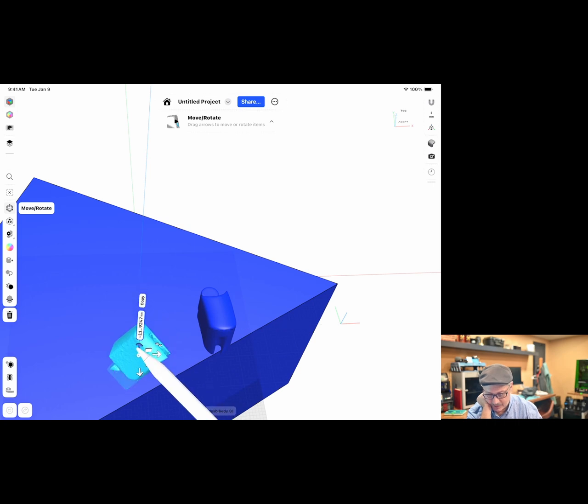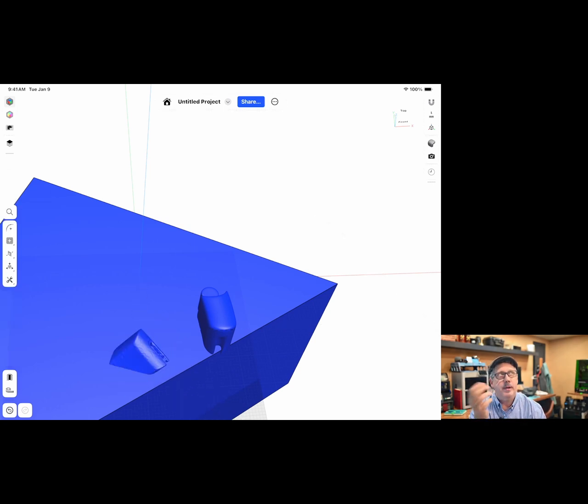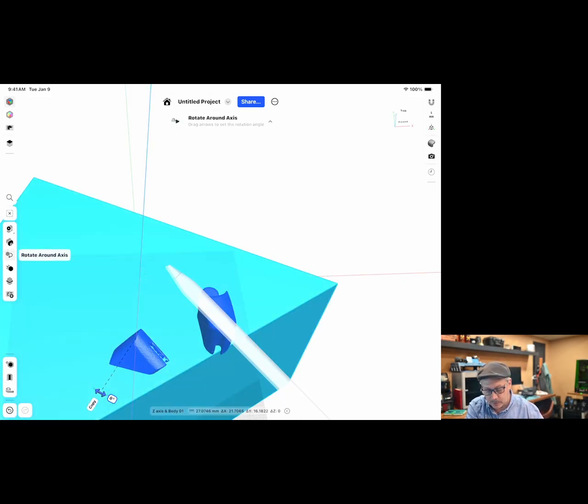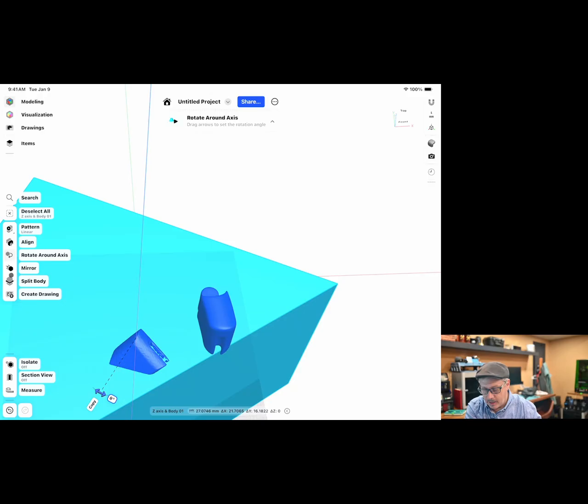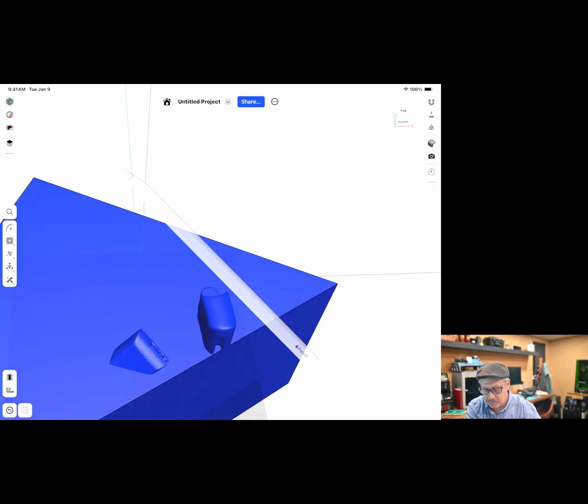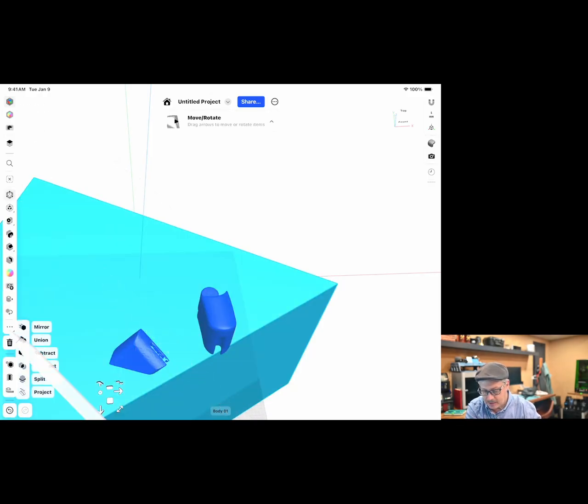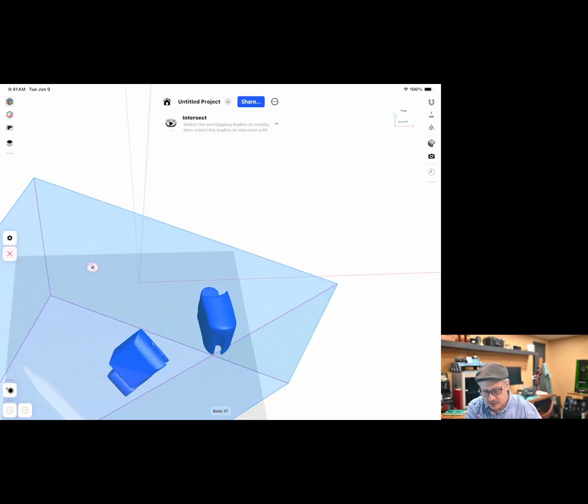Let's plunge it there, and then let's see if we can do an intersection point. Take this, go to intersect, click that, and you get "sheet body can't be selected." You see that at the top of the screen? You think, oh, it's not a problem with mesh, it's a problem with sheets. It likes manifold mesh. Well, don't waste your time.